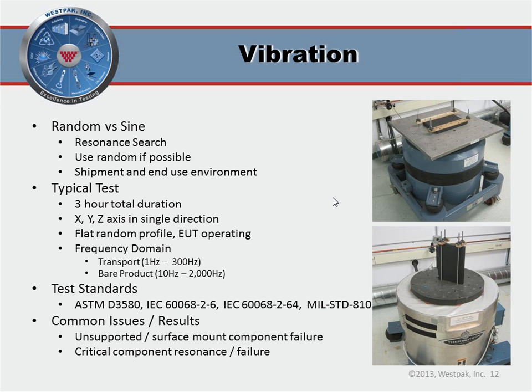Typical procedures will, again, look at all three directions, and because this is both a positive and negative input, we simply would limit the testing to the three orthogonal axes, X, Y, and Z. And anywhere between 1 and 3 hours per axis is a typical test. If you're just looking for resonance, it doesn't take very long. If you're trying to find the results of resonance, in other words, how much fatigue does this product generate, then the time duration gets to be more important.